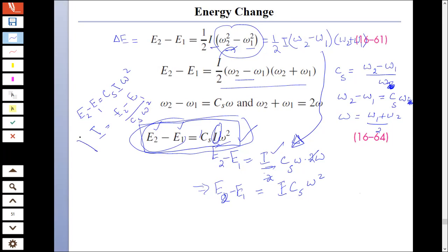So I can go ahead and find the mass of the flywheel from this equation, that what kind of flywheel am I going to use in order to work with the energy variation that I have in this case. So this is how we would design a flywheel for a certain range of energy fluctuation.